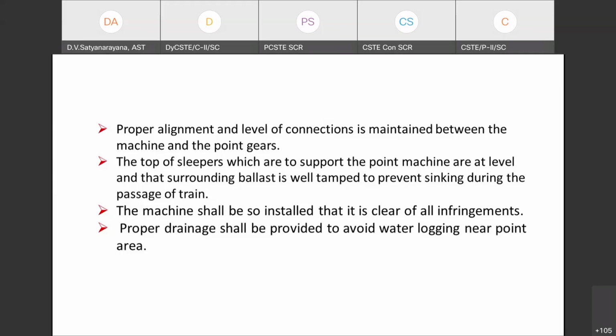This is possible when the slides are physically inspected, and the slide having the closed switch in the correct orientation is marked, then connected to the concerned switch. You should not use thumb rules, such as the machine is on the left side or the machine is on the right side. You cannot go for thumb rules for this. For each and every point, we have to inspect the switch notches on the switches, then mark it and connect it. So 100% we have to physically ensure, sir.